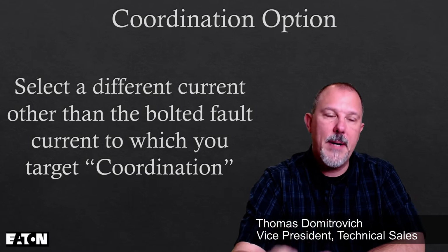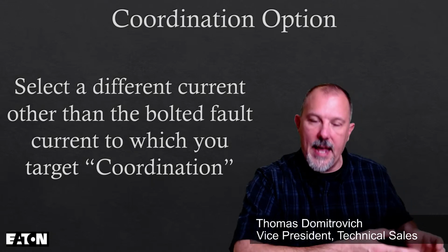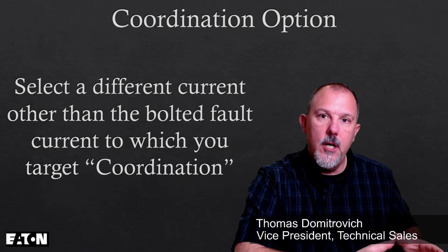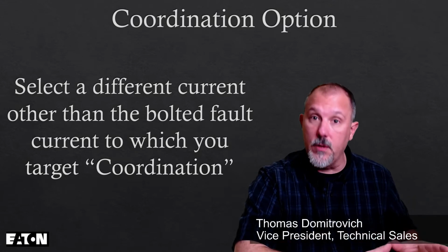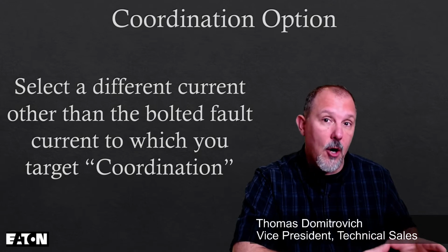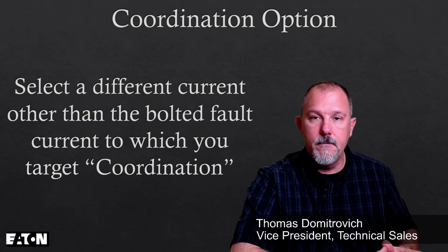My goal as a power systems engineer was to help them understand what they have. So if they didn't selectively coordinate, I would look at the most common fault in a power distribution system, which would be the arcing fault current, and tell them whether or not they would coordinate to that value.